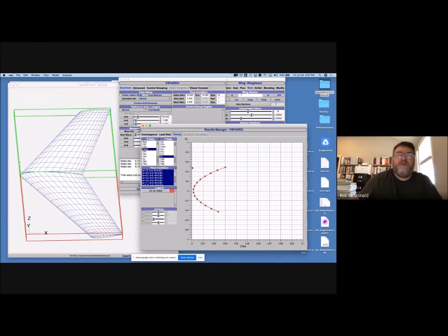The reason it's called a drag polar is that when you plot it this way, with lift on the vertical axis and drag on the horizontal axis, if you were to plot the total resultant aerodynamic force on a body, whether it's a wing or a plate or an airplane, in polar coordinates, you get this. Again, these axes are weird, right? The x-axis is much, much more zoomed in than the y-axis. But if you drew a line from the origin at 0, 0 to a point on this curve, and figured out the angle with equal axes, and in fact we can force them to be equal axes, we'll do this real quick. Everything's real quick.